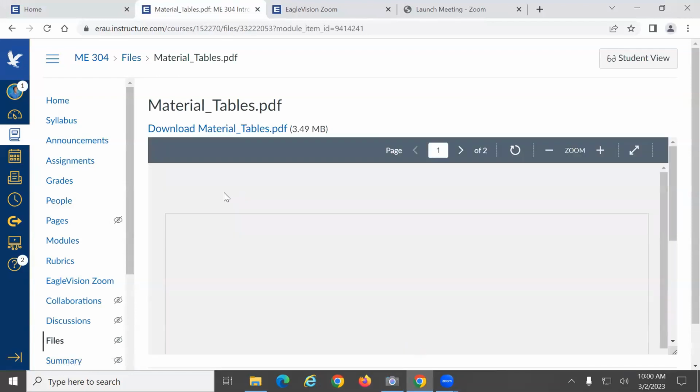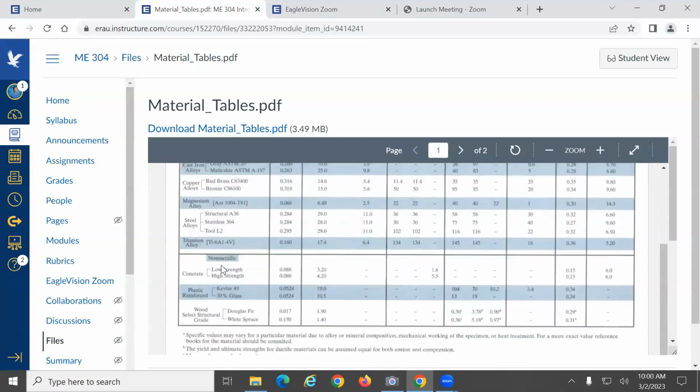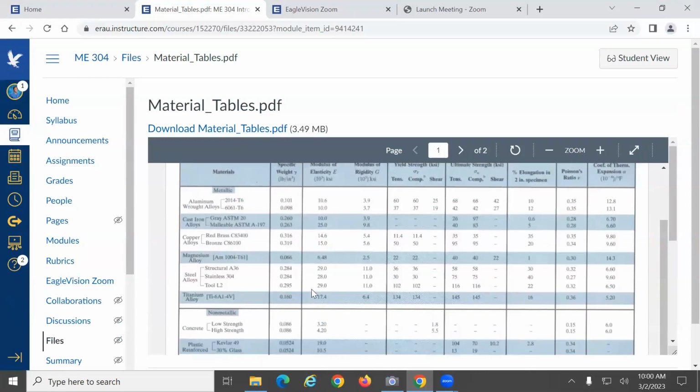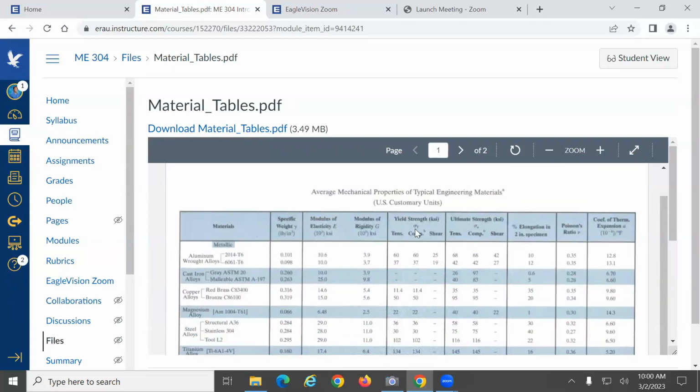Okay, so perfect. So let's see, aluminum material, steel. About A34. So let's say A36. So for A36, what will be the yield stress? So you see, we can use either the yield stress or the ultimate stress. Which one do you want to use? Yield will be safer. Okay. So let's use the yield. We have A36 will be 36 KSI. Okay.